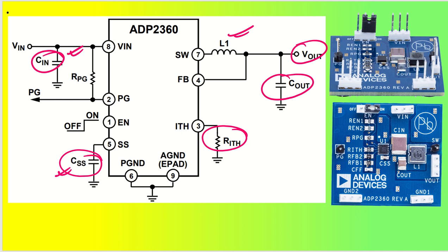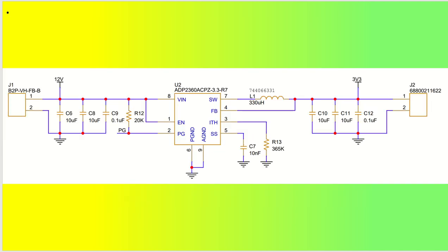I have done 3 implementations for you. First of all, this is a fixed regulator, fixed version. This is going to give you 3.3 volt output with 50 milliamperes of current. It is set to 100 milliamperes of current at I peak, so it will give you half of that, that is 50 milliamperes, right?